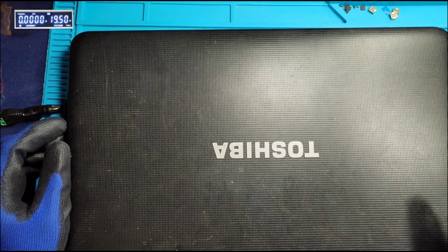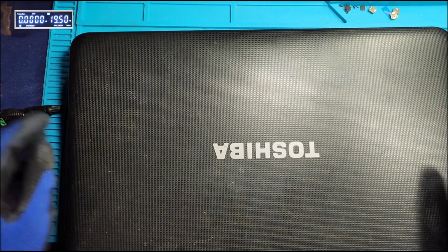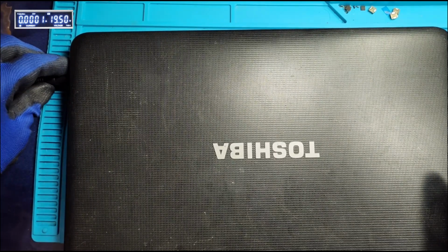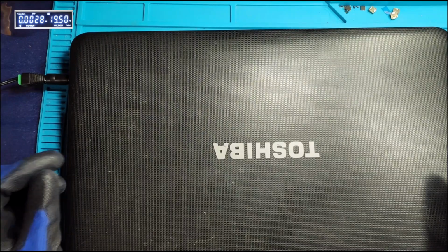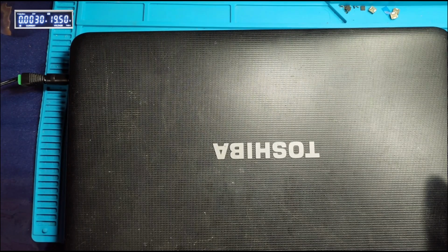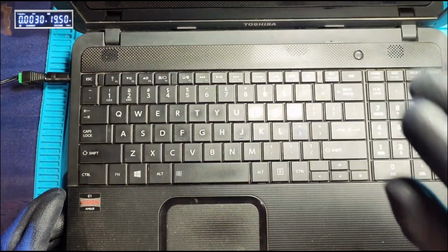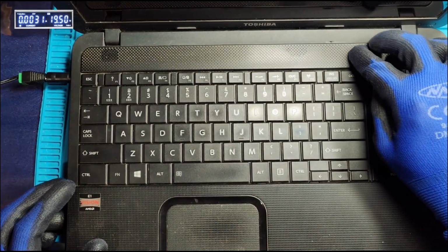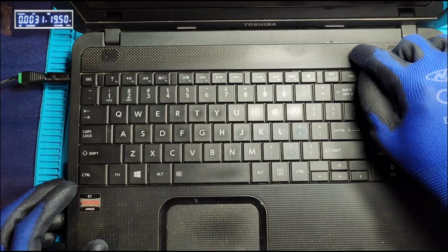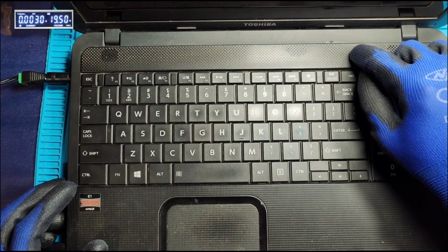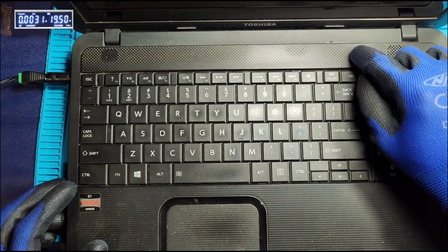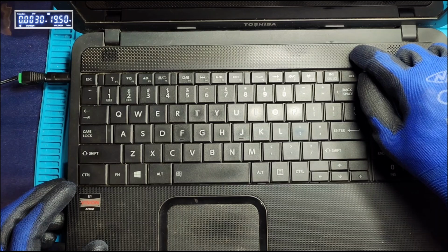Okay, now the display of the power supply is visible to you, so let me connect the adapter. Now the adapter is connected and you can see the ampere reading is around 3 milliamps. So let me open the laptop and try to press the power button here. Now I'm pressing the power button and there's no response on the ampere reading. So there's no response to the power button here.